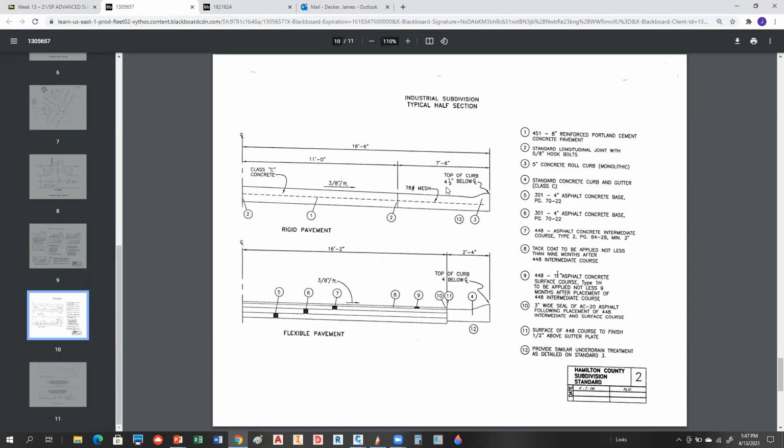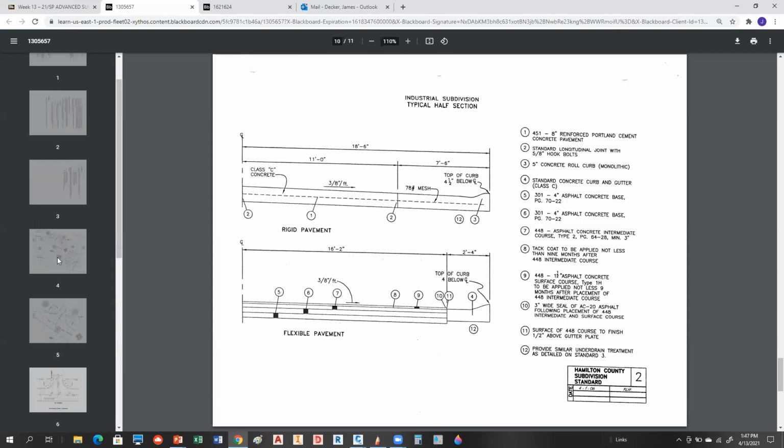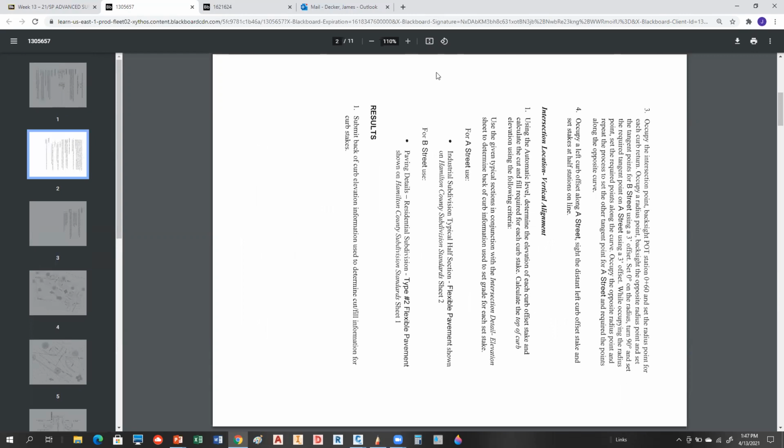But you notice it says 4 inches below the center line or 4.5. See that? Yeah. So I'm telling you which one of those to use. So we would take 4 inches plus or minus whatever you calculated, and that would get you the elevation. I have to be careful what I'm saying there. I'll tell you what it tells you up here which one we're using.